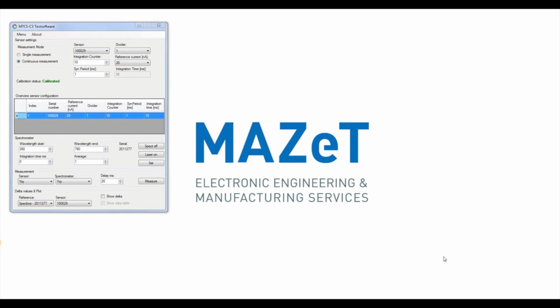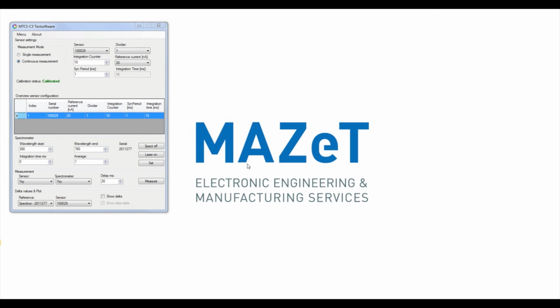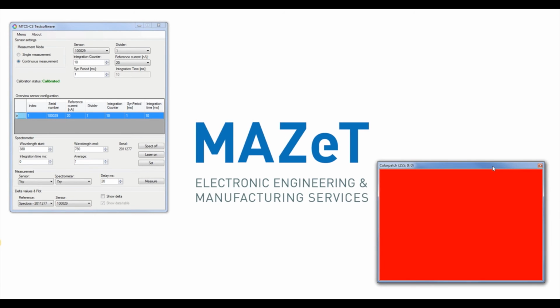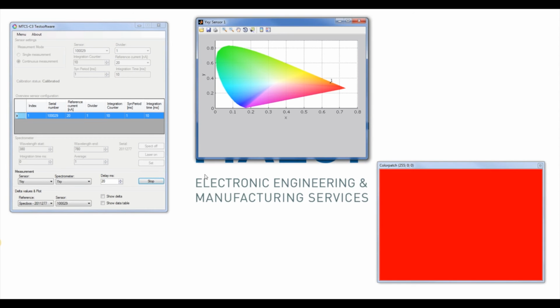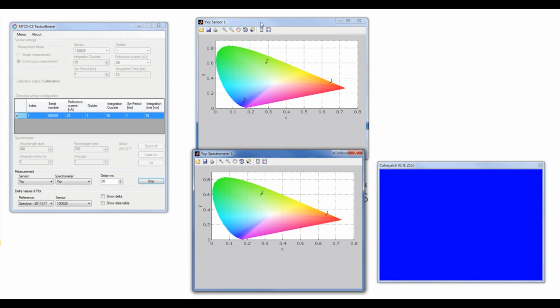After successful calibration, it is possible to use a spectrometer to perform comparison measurements. Using a color patch, simply perform measurements with the sensor and spectrometer to measure the current delta values. All measurements are logged and can be exported for future use. This is also an ideal method to test the accuracy and see if further optimization of the calibration is required or not.